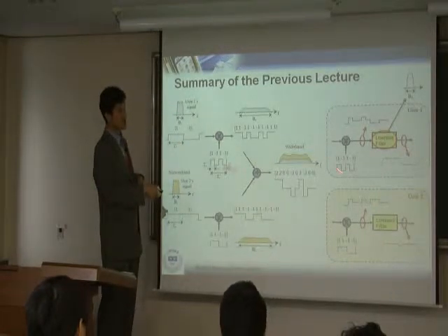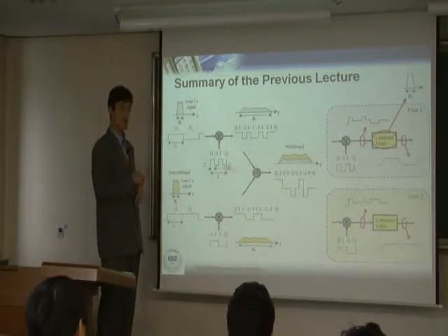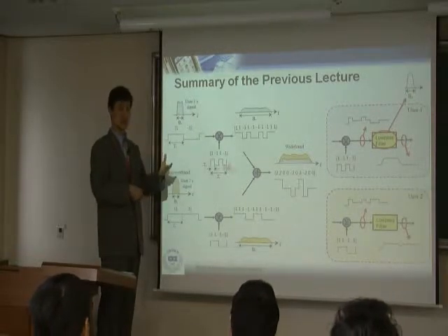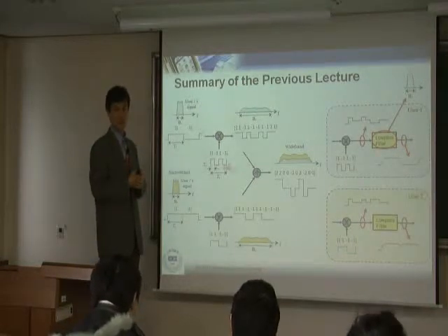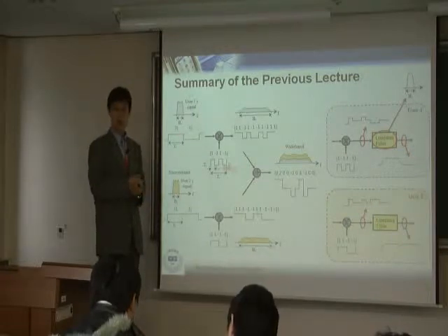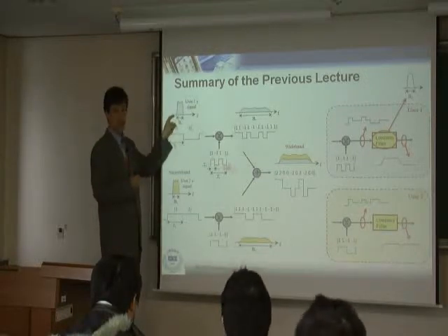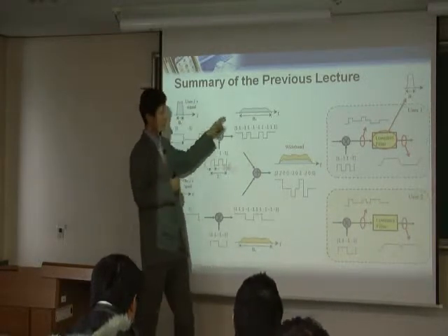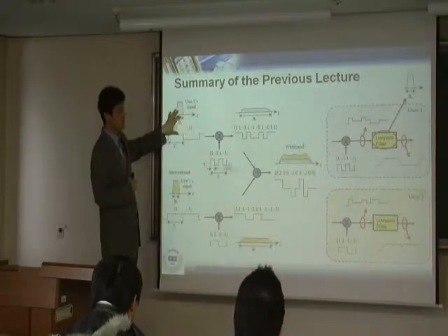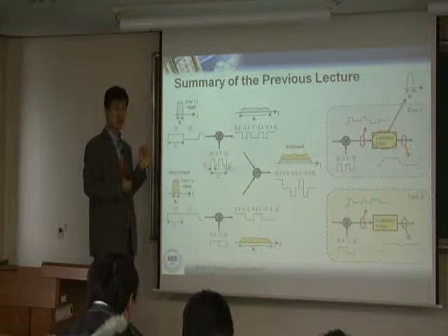So that's why the base station has to tell each of them, okay, it looks like you are close by, okay? It looks like you are far away, okay? This guy has to tell them. That's one of the system parameters, okay? That way, this guy understands that, okay, I seem to be close by, so I have to reduce my transmit power. But even that transmit power is not accurate because we are talking about a fading channel, right? This guy decides its own transmit power based on the estimated distance, but that power is still not accurate.